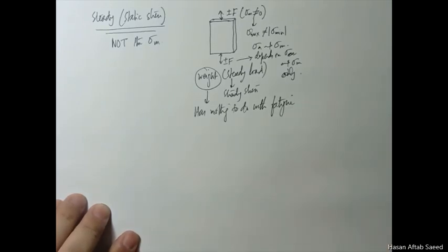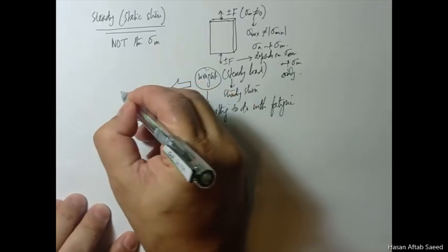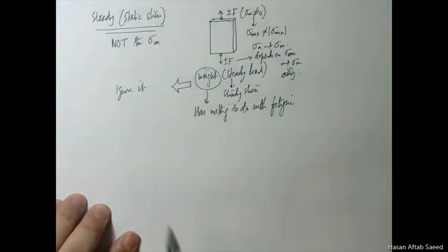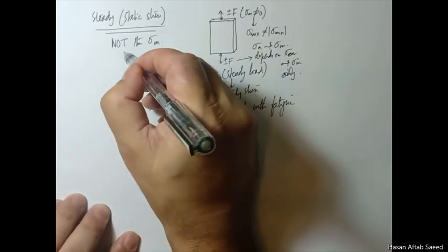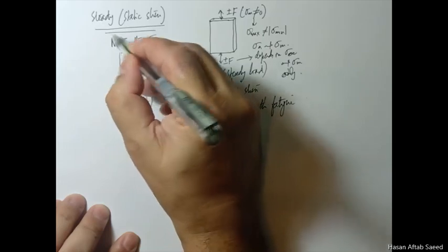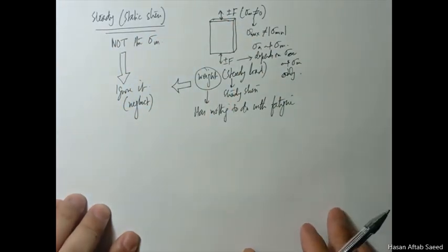If it's a fatigue analysis that you are carrying out, then you will ignore it. This static stress is neglected. You don't consider it in fatigue analysis.